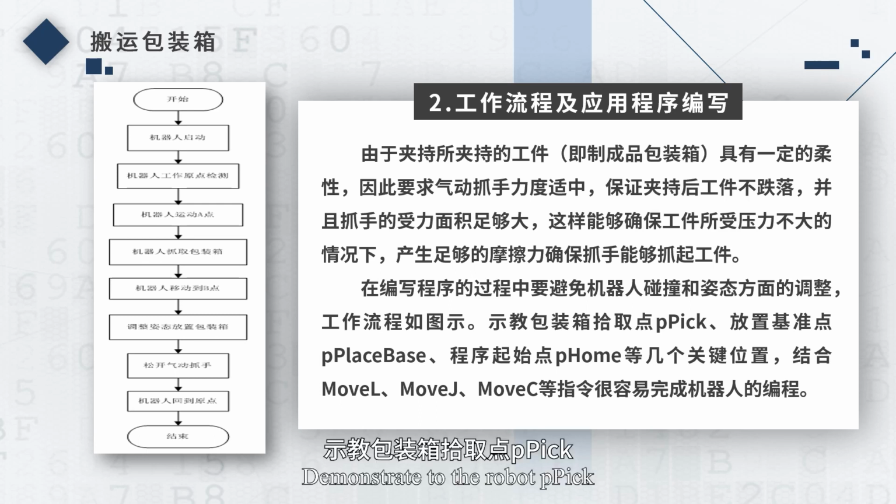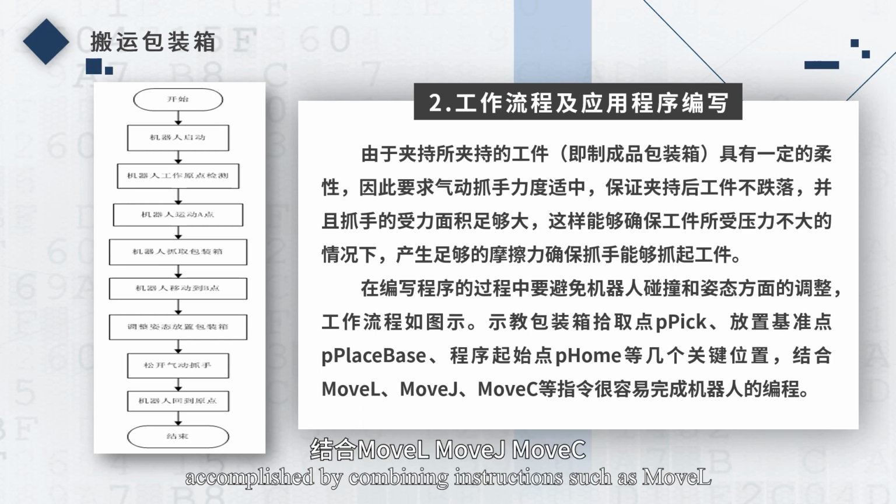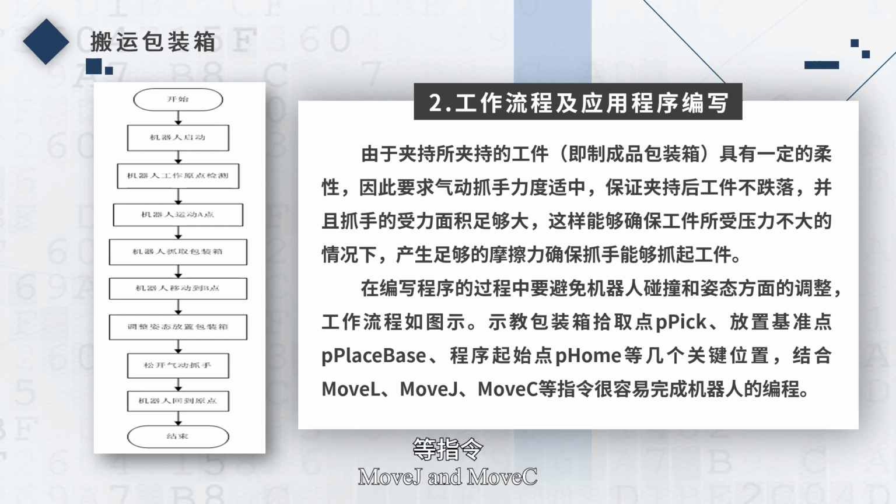End. Demonstrate to the robot P-pick, P-place, P-home, as well as several other key positions, accomplished by combining instructions such as MoveL, MoveJ, and MoveC. Programming of the robot is easily accomplished.